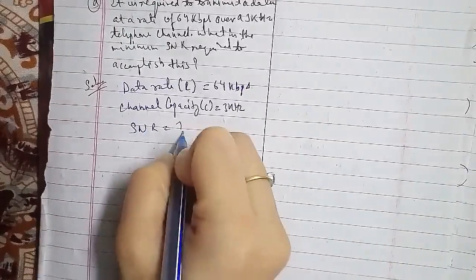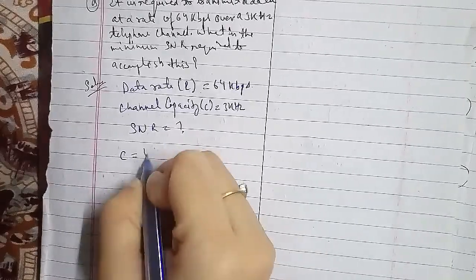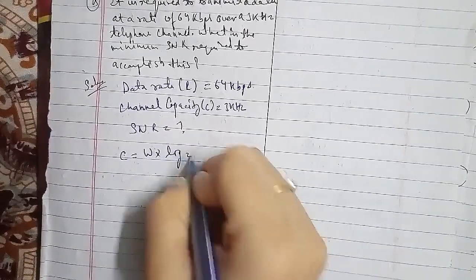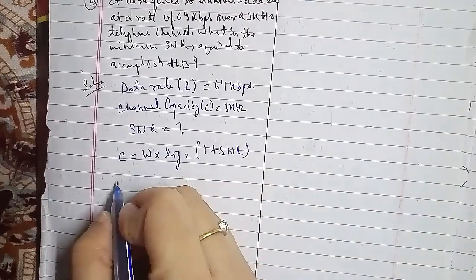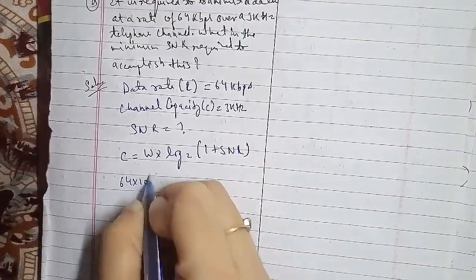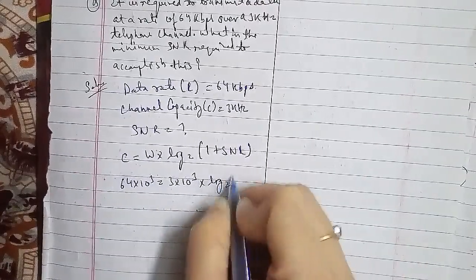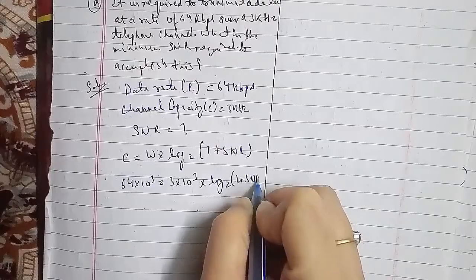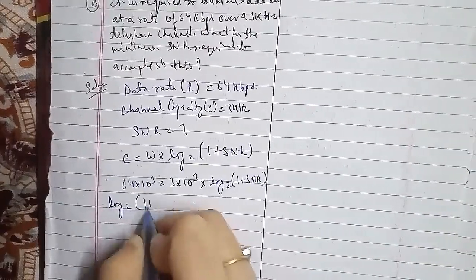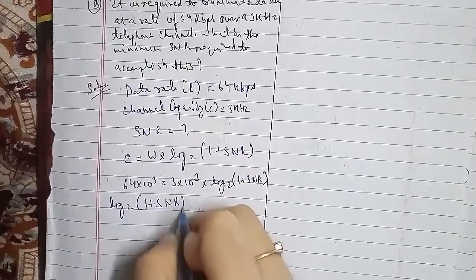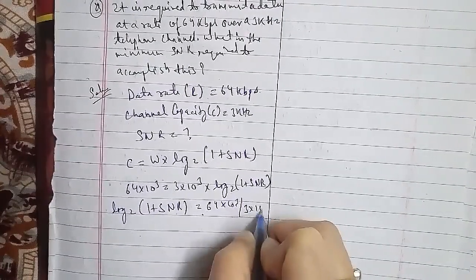Then we have SNR min in dB equals 10 log base 10 of SNR. That is 10 log 10 of 2.64 into 10 to the power 6, and of course we get 64.2 dB. So this will be the right answer, and this is how you find it.